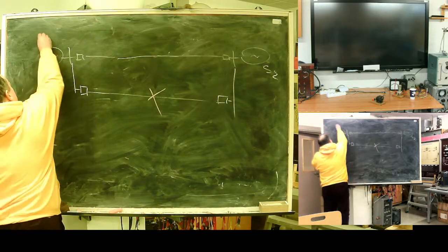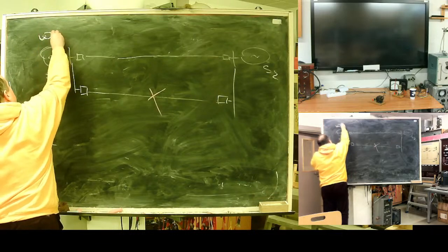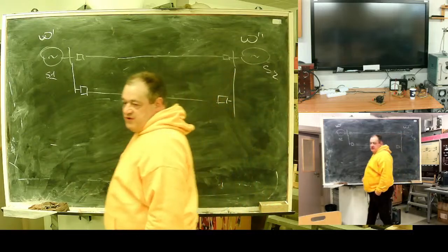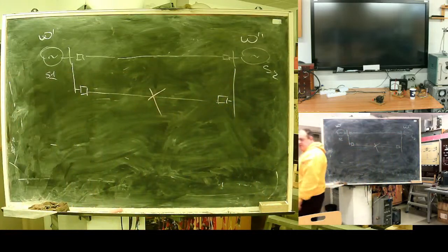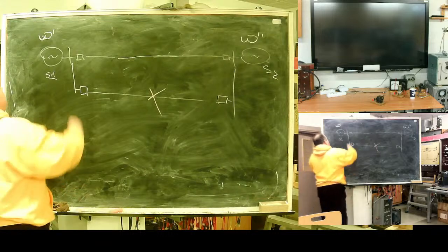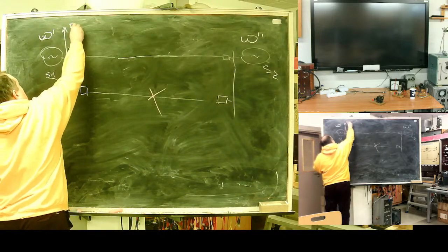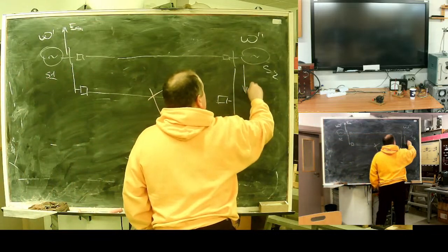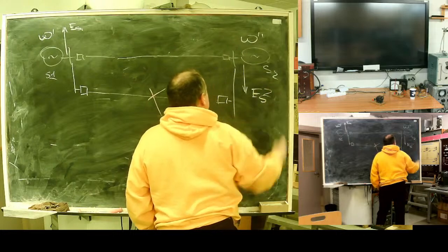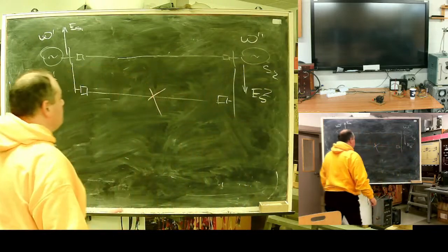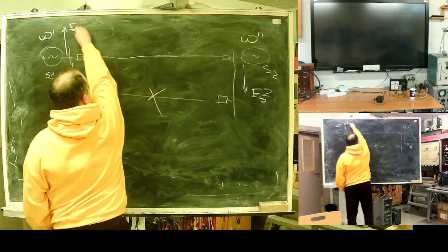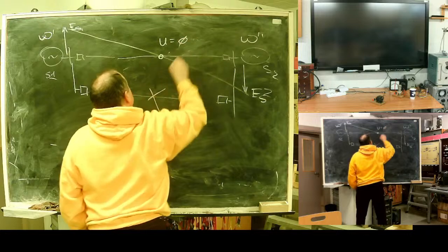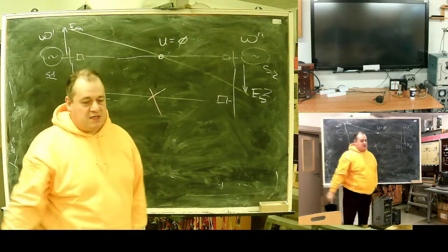There will be actually two different frequencies in parts of the system. And we will see the moment when system 1, let's say, goes up, and system 2 at this moment looks down. It's the worst case. If you connect them, this is the point where voltage is 0. It's called the electrical center of swings.